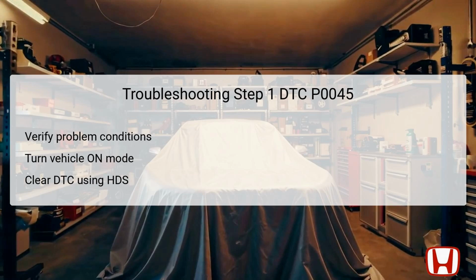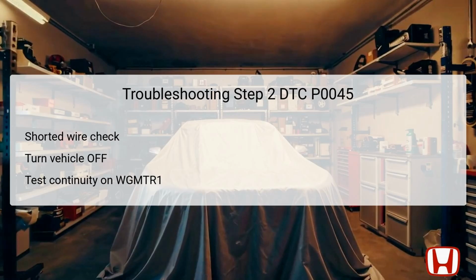This testing procedure is crucial to see if DTC P0045 reappears, helping differentiate between a persistent issue and an intermittent one. Make sure to select the electric wastegate option in the HDS menu and check for any present DTCs, guiding the next steps effectively. Moving on to the second troubleshooting step for DTC P0045, begin by turning the vehicle to the off or lock mode.